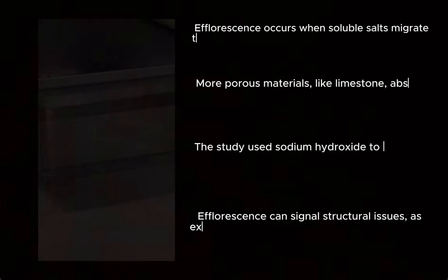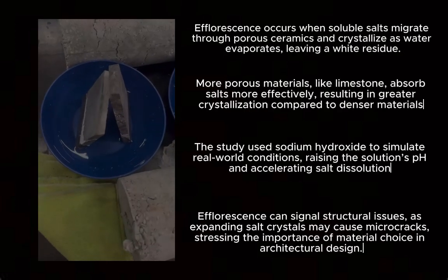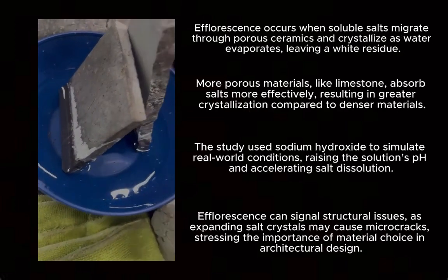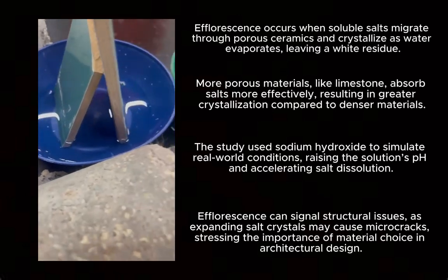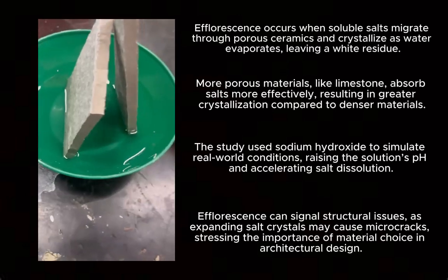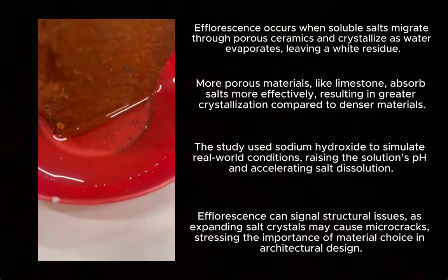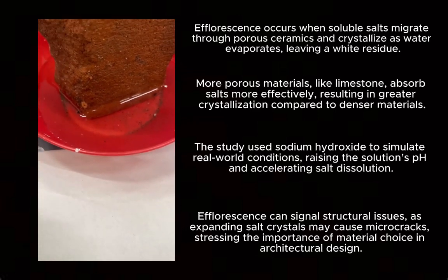Our analysis showed that after 2 and 24 hours of exposure to sodium sulfate, visible efflorescence developed on ceramic surfaces. This white powdery residue forms when soluble salts migrate through the ceramic's porous structures and crystallize as water evaporates. The degree of efflorescence varied by ceramic type.